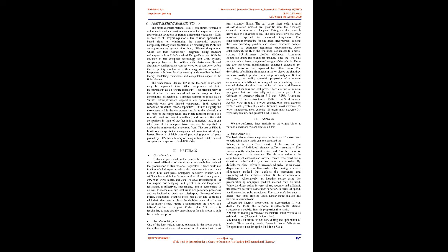The finite element method, FEM, sometimes referred to as finite element analysis, is a numerical technique for finding approximate solutions of partial differential equations, PDE, as well as of integral equations. The solution approach is based either on eliminating the differential equation completely, steady-state problems, or rendering the PDE into an approximating system of ordinary differential equations, which are then numerically integrated using standard techniques such as Euler's method, Runge-Kutta, etc.